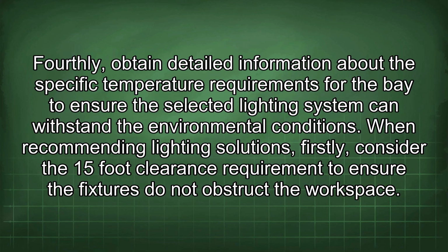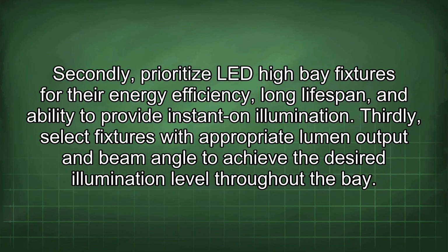When recommending lighting solutions, firstly, consider the 15-foot clearance requirement to ensure the fixtures do not obstruct the workspace. Secondly, prioritize LED high bay fixtures for their energy efficiency, long lifespan, and ability to provide instant-on illumination. Thirdly, select fixtures with appropriate lumen output and beam angle to achieve the desired illumination level throughout the bay.